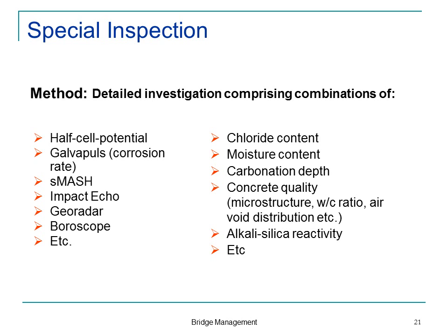So if we have a deterioration, then we should probably check the quality of the concrete, and we do that by taking samples.